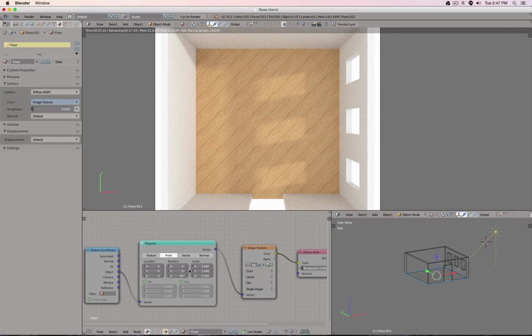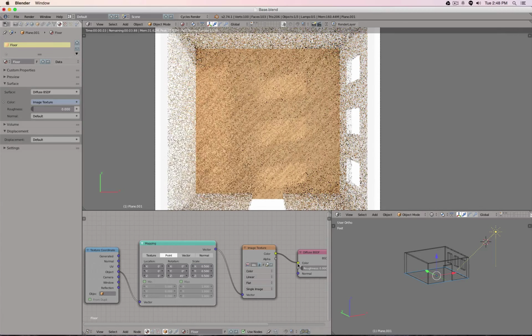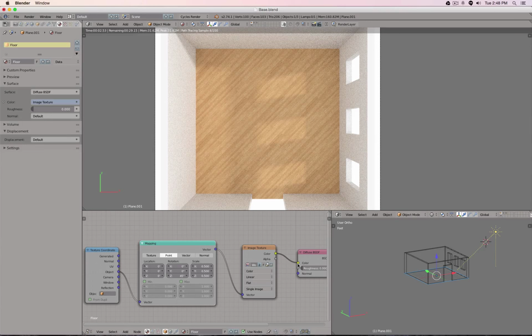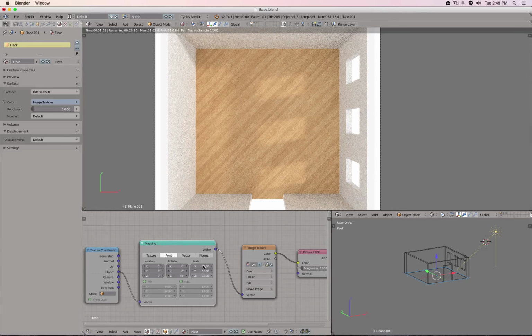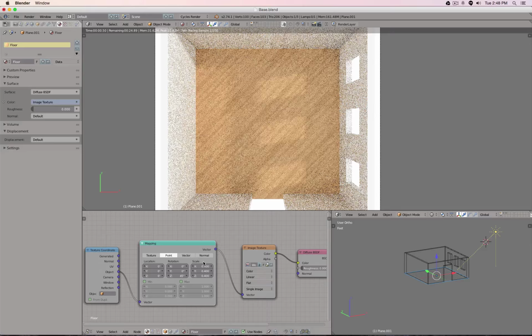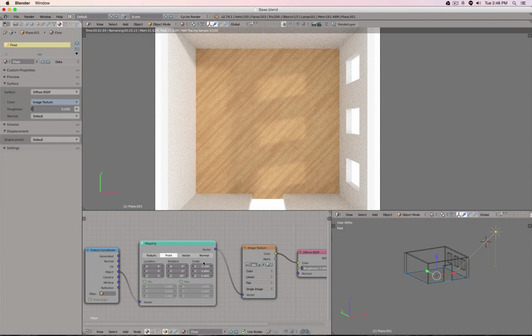Very easy. And maybe the size is too small, so I can left mouse button click, hold, and drag down to the Z, release my mouse button, and then type in 0.5. You see all three values are adjusted at once. Really nice. 0.3. This is maybe a tick too big, so 0.4. Okay. And you see this is actually starting to look pretty nice.